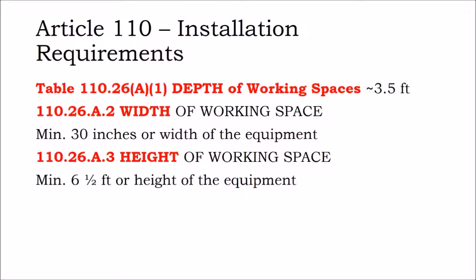And so if you just keep in the back of your head, well, in the depth from the face of the panel, you need to have around 3.5 feet of working space. And if the room is feeling particularly tight to you, rather than the panels being back to back, or depending on what is on the back of that panel, you may need an additional 1/2 foot.